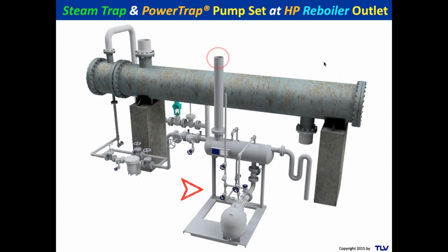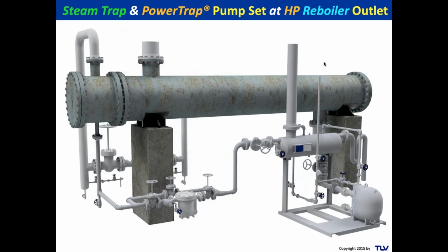and it might have to go to a vented receiver, and yes, you might have to do something with that vent. You might use a pinch analysis sort of idea and try to use that to heat some of the cold stream. You might condense it or something like that, and then you just pump it away. But there's your simple pump set to pump it away, right there. It's not a bad situation to do that. It's a lot better than blowing 28,000 pounds an hour of steam into your return header and creating all that back pressure and all that hammering and damage to the piping system.